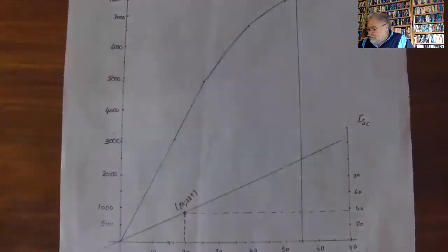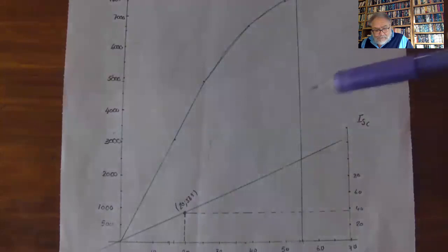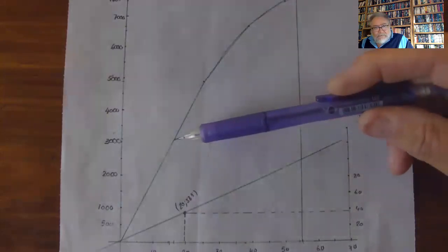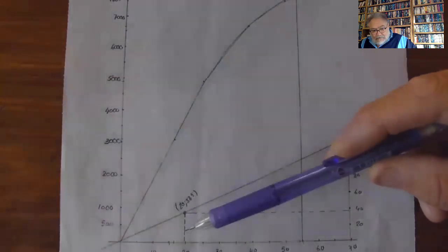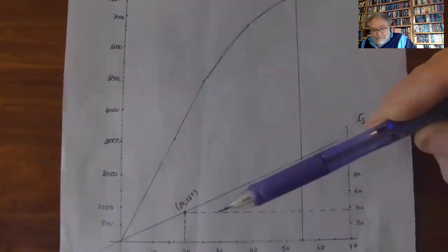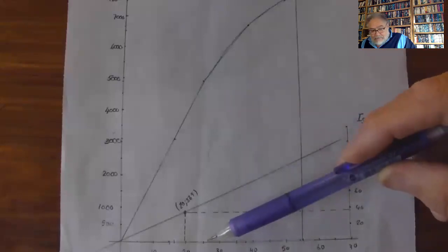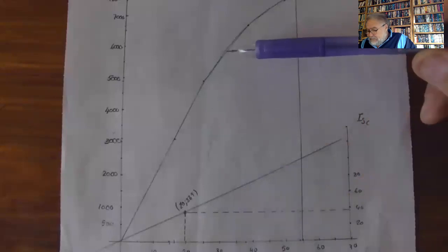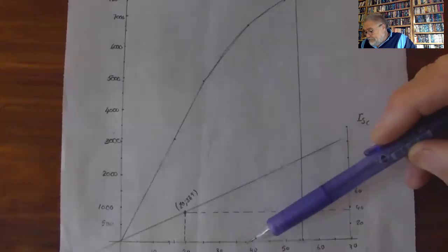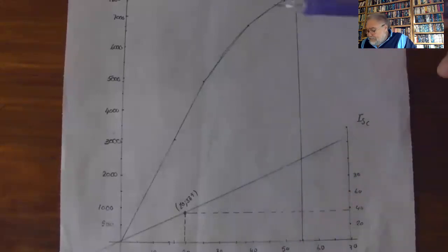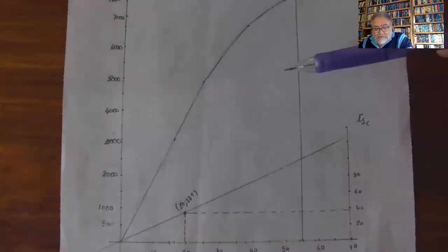There you can see the first point is 3100 at 16 amps, and then 4900 at 25 amps, and 6600 at 37.5, and 7500 against 50. And then for the short circuit, a field current of 20 amp was necessary to circulate full